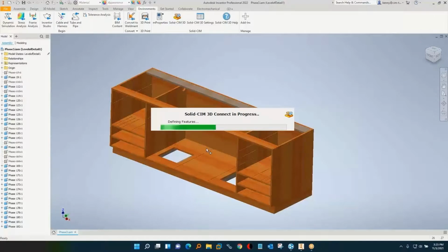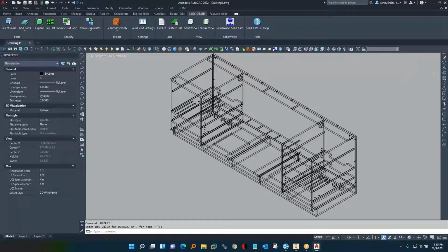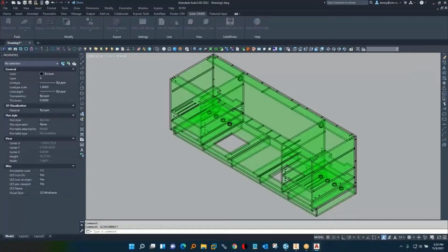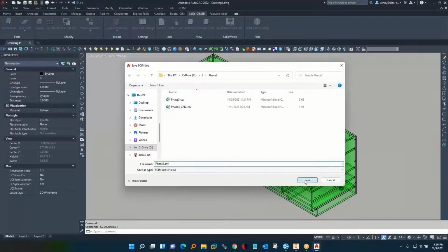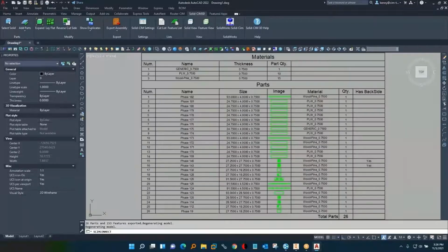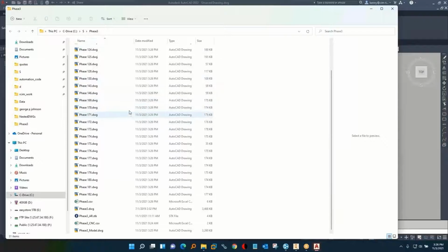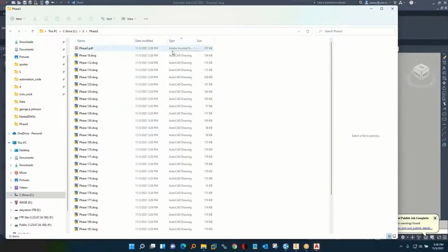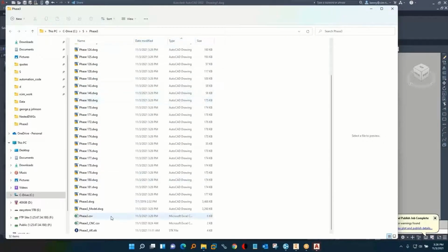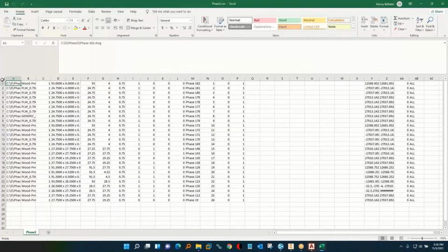With one button click, we're going to make the individual parts with geometry on different layers. So these parts become intelligent geometry. For example, a dado is going to be a rectangle on layer dado. It picks up the depth. It makes a cut list for us that has the name of the parts, the material, and the quantity, and the panel dimensions. And there you see them in those columns.